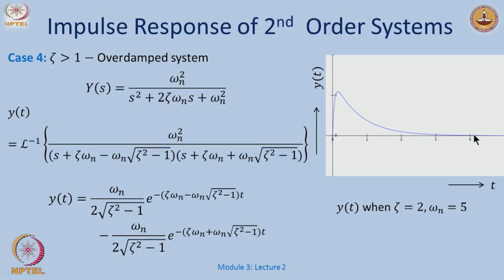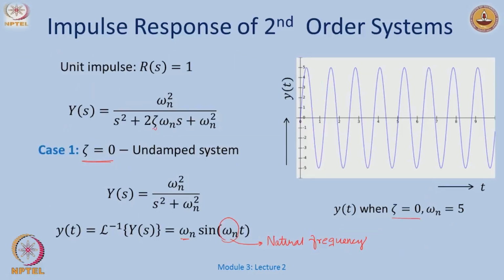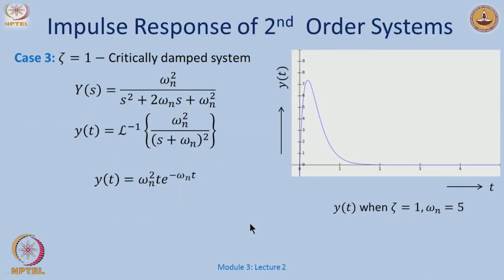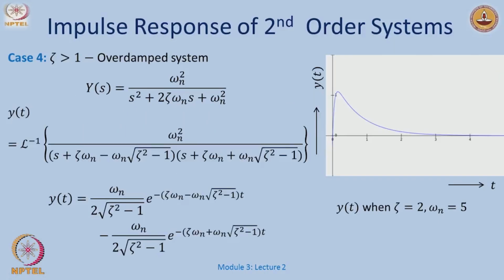So, we saw 3 cases now, right. Actually 4 cases. First is the undamped case, where the system just oscillates at the natural frequency. Then I had oscillations, but they just die down because of this exponentially decaying term here, and they still oscillate at a new frequency, which zeta defines. Again, you can just put zeta equal to 0 and it will go back to the natural frequency. Okay, and then a critically damped system and what we call an overdamped system.